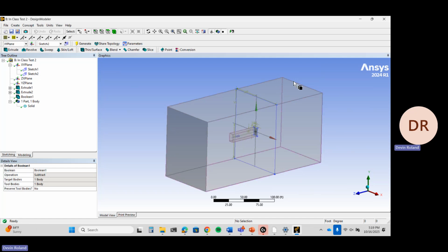Are they frozen for both of those, or is the second? I left them both frozen and also put no for the merge topology. Yeah, I think you might be able to leave the first one as default, and for the second one, do frozen and not merging topology. But just to be safe, I went into them both that way. That way it would not have any risk.